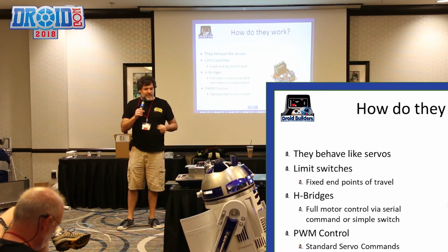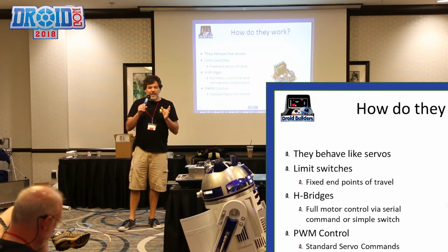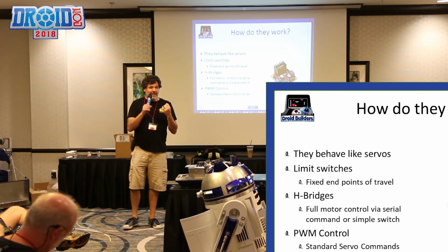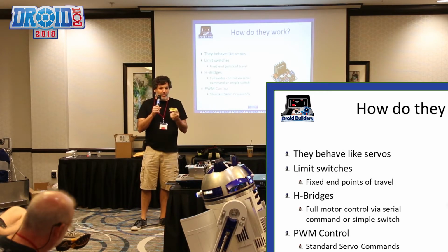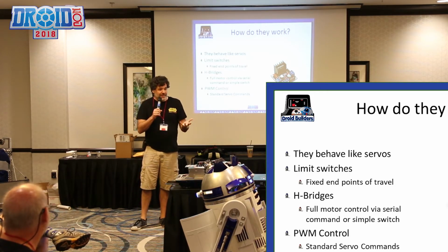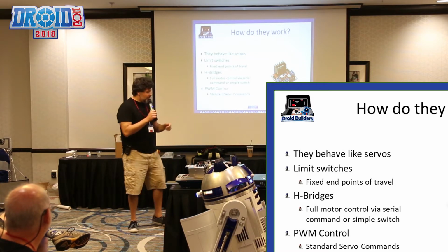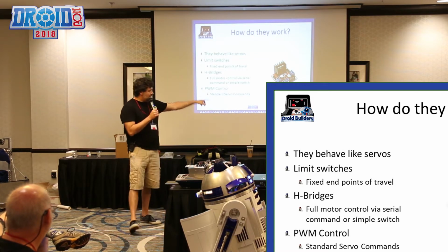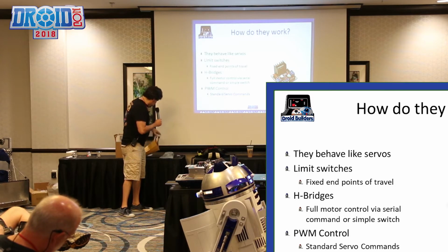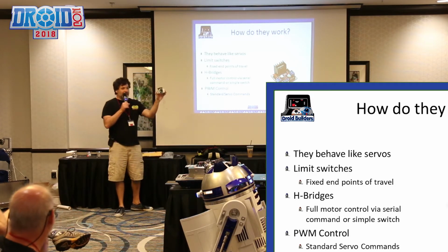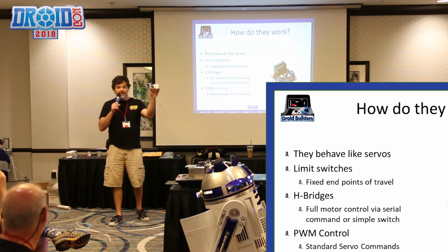And typically if you have an actuator that does not have feedback on it like a servo, you'll need an H bridge to tell it when to stop or when you want to turn it on and off. So that's one thing with those. And this is your typical L298 H bridge. It's actually very small. I'm going to pull this out and show it. That's it on the back here of this block.